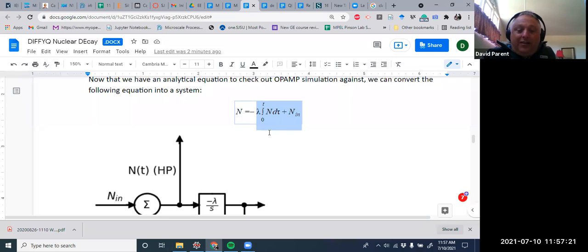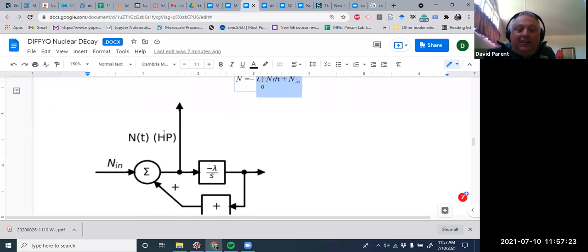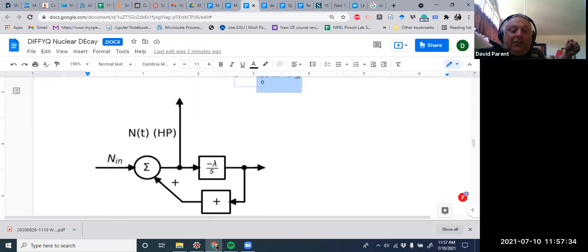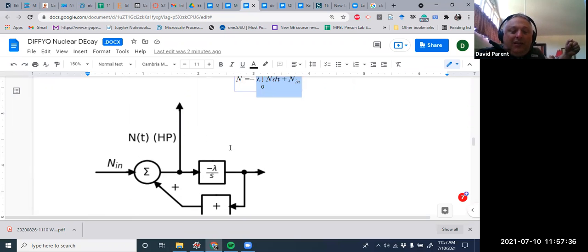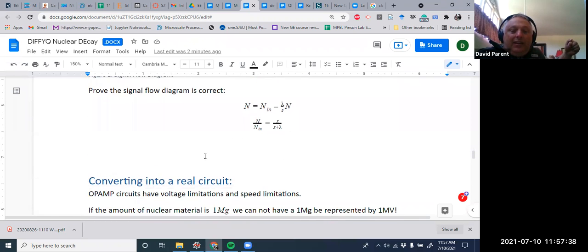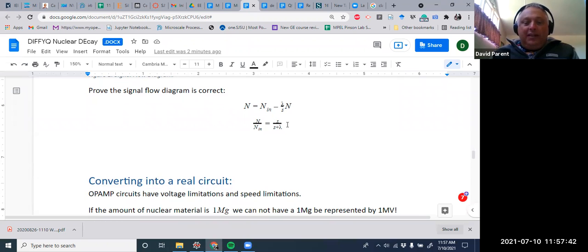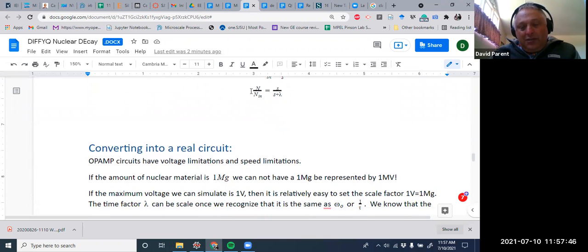In an interesting way, where we're taking it is the high pass node. If this was just 1 over S and I was taking it here, it'd be a first order low pass filter. So I've just put that there, and I go through and check that I'm getting what I'm supposed to be getting, which is S divided by S plus lambda, a high pass function.